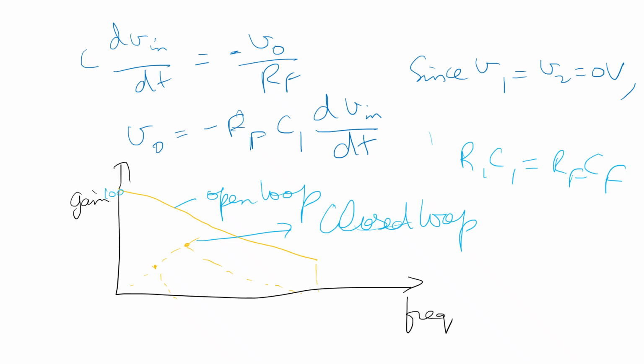Generally, the value of FB and in turn R1, C1 and RF CF values should be selected such that the initial frequencies FA, FB and FC are lesser. The gain of the circuit increases with the increase in frequency at a rate of 20 decibels per decade. This makes the circuit unstable. Also, the input impedance XC decreases with increase in frequency, which makes the circuit very susceptible to high frequency noise. When amplified, this noise can completely override the differentiated output signal.